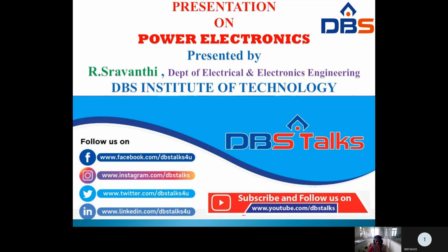negative. At the end of the half cycle, this current reverses and flows through the SCR in opposition to the load current for a small fraction of the negative swing, till the total current through the SCR becomes zero. The SCR will turn off when the resonant circuit current is just greater than the load current. The SCR is turned off if it remains reverse biased for a time tq greater than t off, and the rate of rise of reapplied voltage is less than the rated value.